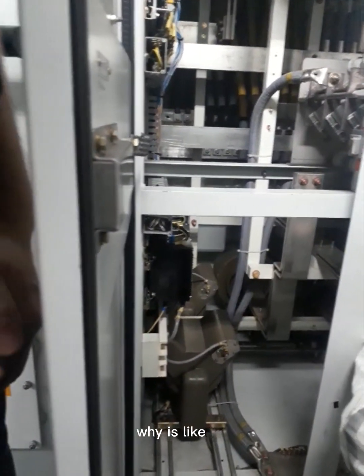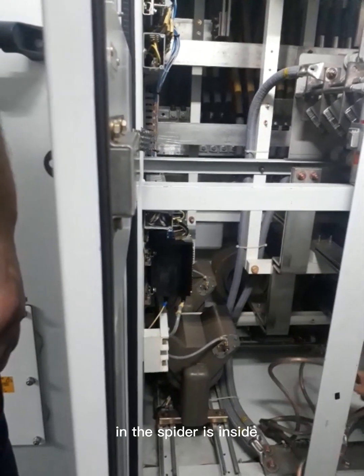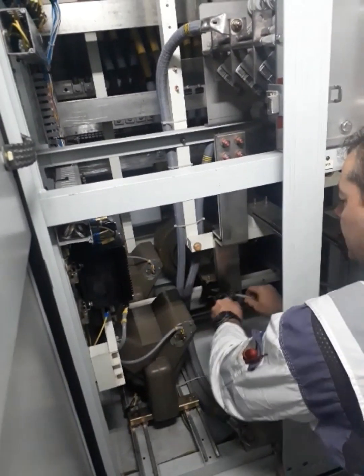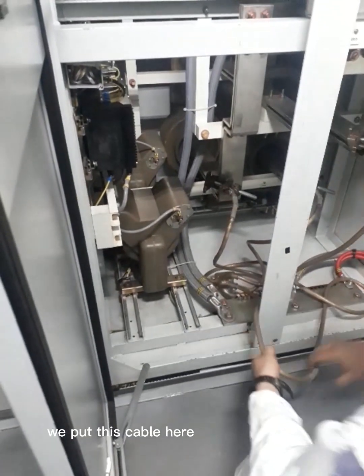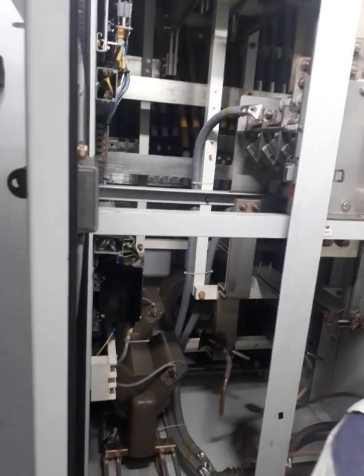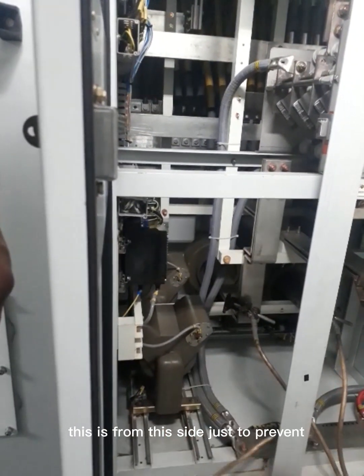Why is it like that? Because if you forgot to remove the spider and the spider is inside, you know, it's connected. You're going to make a big fire here, big short, because really you short the three phases. We put this cable here and this cable here, just if you forgot, you cannot close the doors. If this one is not like that, it's very easy to forget and close the doors, connect everything, and then bam, because you make short with this one. That's why we put like this, three cables one side, this is from this side, just to prevent it.